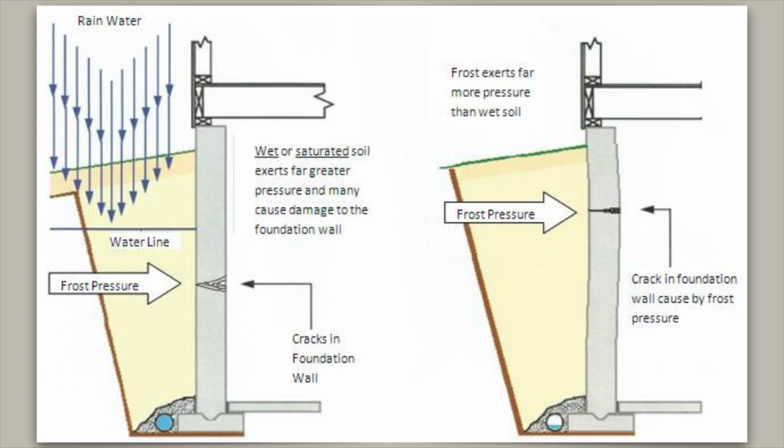To determine if a wall is plumb, take a 4-foot level and lay it against the wall going over the crack. Pin the bottom of the level to the bottom of the wall below the crack. If the top of the level is not touching the wall, then the amount of distance between the level and the wall is how much the bottom of the wall has moved. Always report this as a defect.